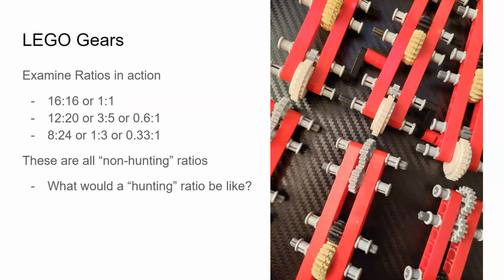This gear, if this tooth that I marked was damaged, then it would start to damage its companion tooth. And in the case of this 1-to-1 ratio, let me see if I could annotate this a little bit. If this tooth here was broken, it would start to cause problems for this tooth right here. And every time it goes around, those 2 damaged teeth would keep hitting each other and keep damaging each other.